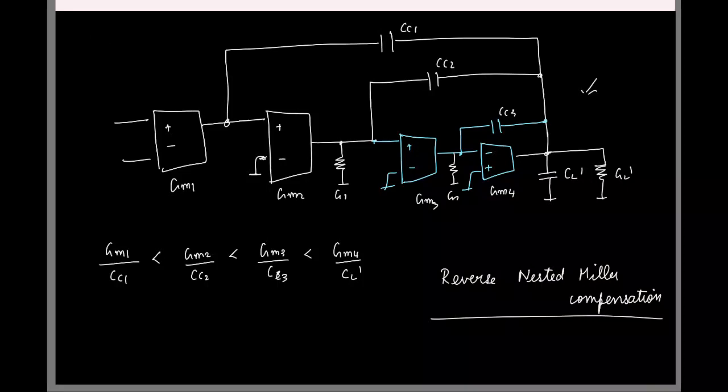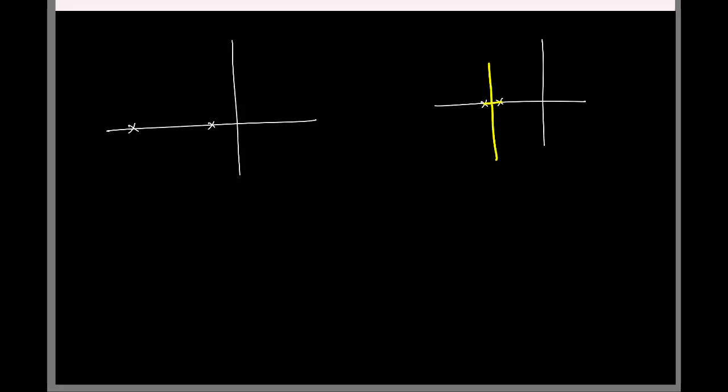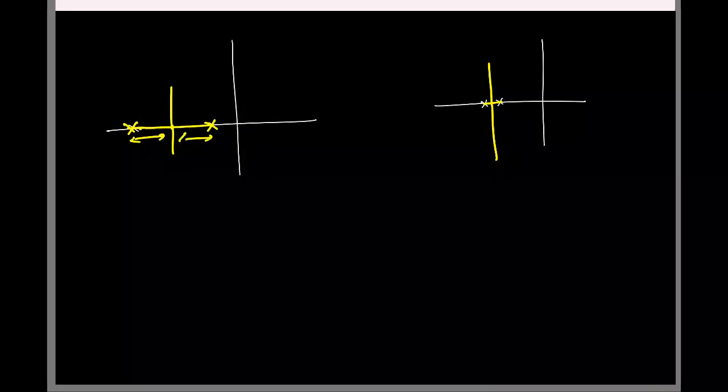Now, when we started off with stabilizing higher order systems, we came up with 2 techniques, if you remember, right? We initially started off by saying that we wanted the closed loop poles on the real axis. For the open loop system, we will have something like this, and the root locus was doing this. We wanted to make sure for a large DC gain, the closed loop poles lie on the real axis, and one way we can ensure it was to keep them far apart initially, so that for a large range of gain, it is lying on the real axis, and that was Miller compensation.